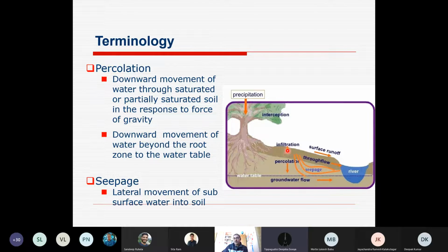Once it has entered the soil, it is moving vertically, that is called percolation. Deep percolation means once it passes a certain depth below the soil, that is beyond the root zone depth, it is deep percolation towards the groundwater. Or it is moving laterally. Lateral doesn't mean that it is moving in this direction only. It is not always perfectly horizontal, but in any path, a radial kind of flow. So it is basically the seepage. It is going laterally, so laterally it may meet the groundwater somewhere, depending on topography, or it is coming up on the surface, say in a depression condition like channels or rivers.